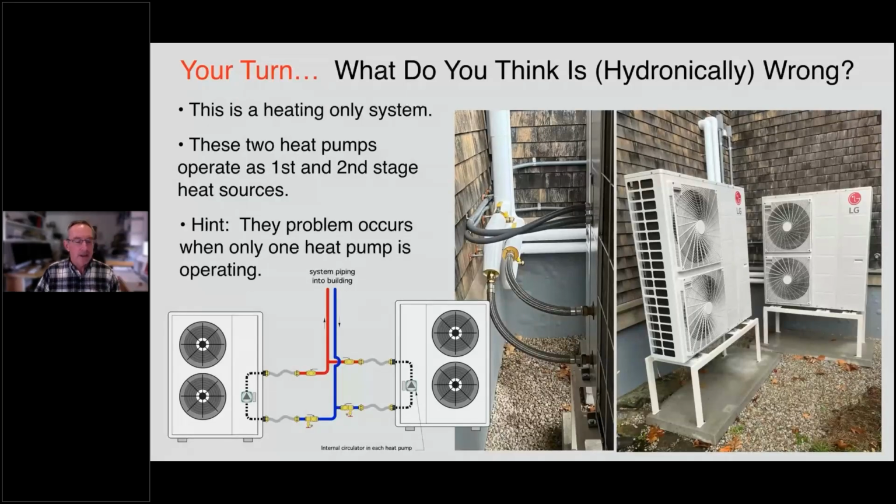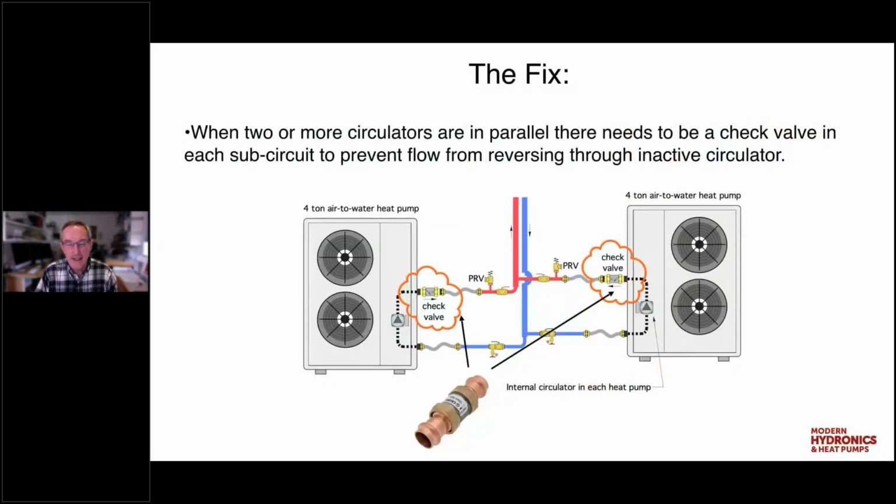Not only is that going to take some heat away from that flow, it's going to mix some cooler fluid, because this is lost heat. Some of that cooler fluid is going to go back into here. So there's nothing good about this. And fortunately, the solution is a check valve. Again, that was pretty easy in this case. But again, nothing wrong with the heat pumps.